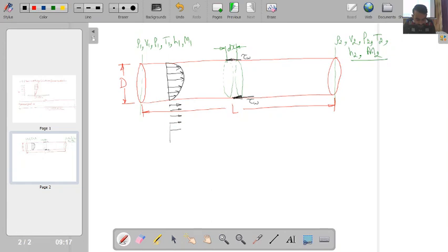Okay, so this will be my average velocity. In actual practice I will be having some different velocity profile. It means variation of the velocity along the radius of the pipe. However, what I am doing over here, because we have to make this situation one dimensional. If I consider the variation of velocity along the radial direction also, then my situation is not one dimensional, because I am having changes along the length of the pipe as well as along the radius of the pipe.